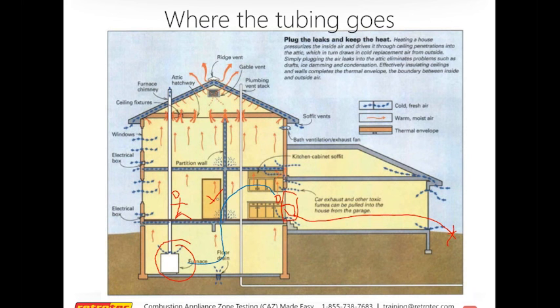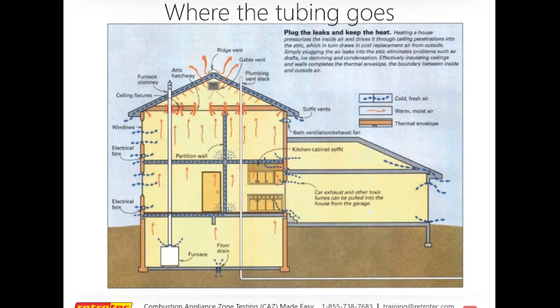Oftentimes, what I used to do when I was using the old standards, the Illinois weatherization standards, which, as Kelly pointed out, were different for the state I'm from, Chicago, than for other states, we used to ask that if it was a cold day, I would depressurize just a little bit to cool off the flue, because the furnace was probably running and the flue pipe was probably warm. So I would depressurize for a few minutes after I turned off the appliance, suck some of that cold air out and cool it off. So you might want to do that as well.